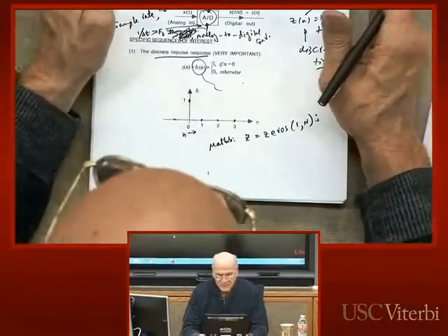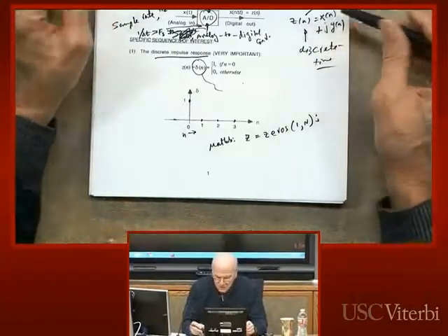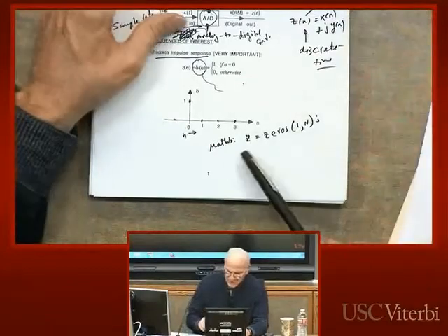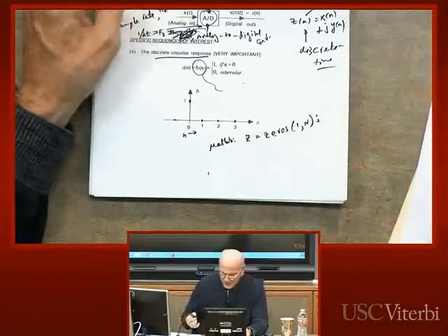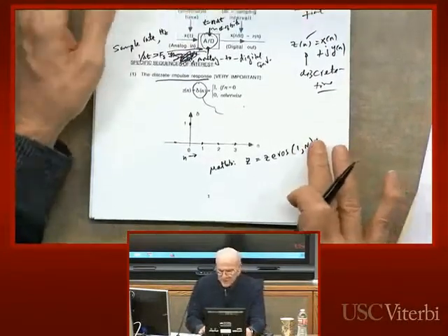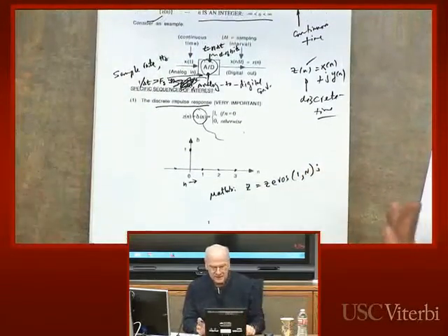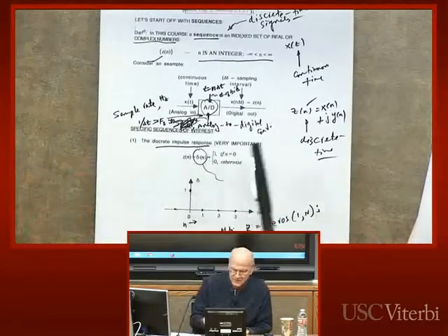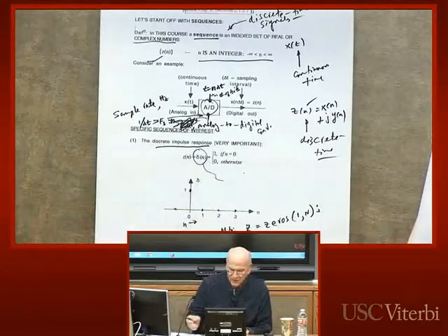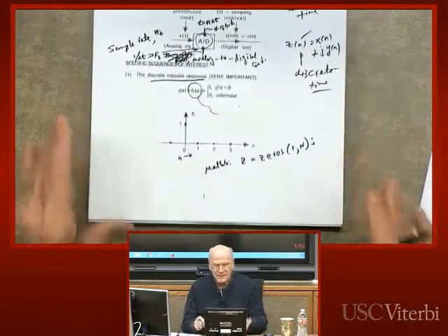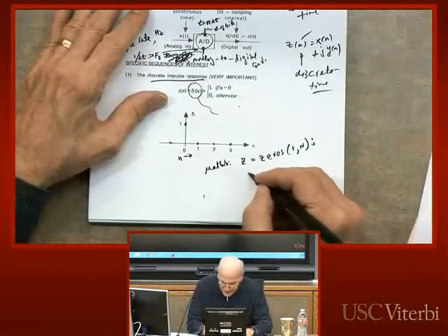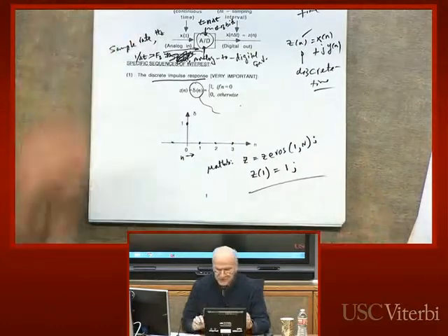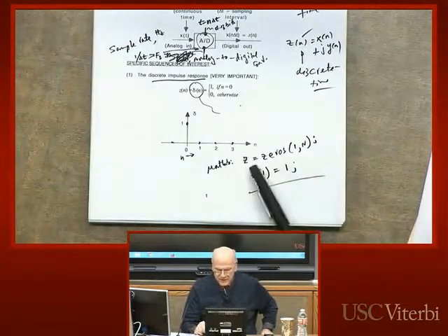Even in Matlab, some of the digital filters, remember what I was calling the IIR, infinite impulse response filters, you have to have a large enough number of points, because in Matlab everything's finite. Mathematically, the impulse response is defined to be infinitely long, but in Matlab it's only finite. Oh, here's the other part. This is how I generate z of 1 equals 1. So you overwrite the 0. This is a simple way to generate the impulse response.